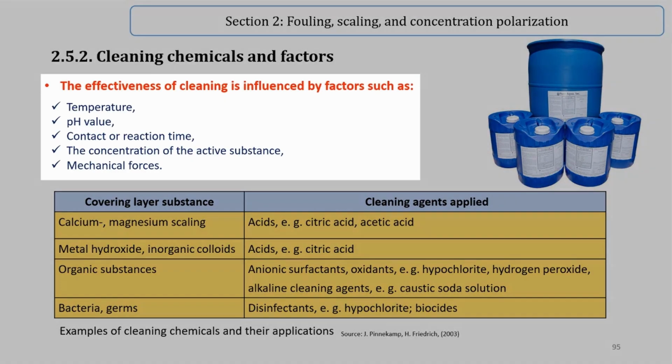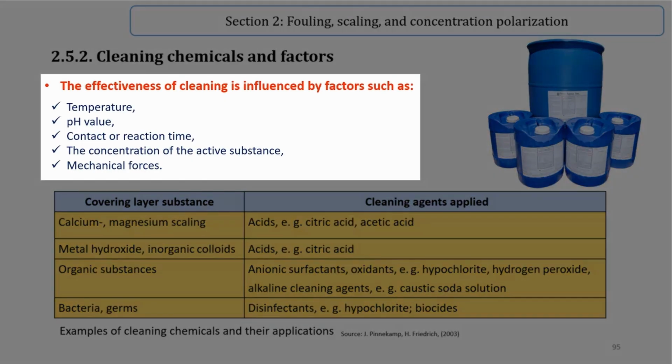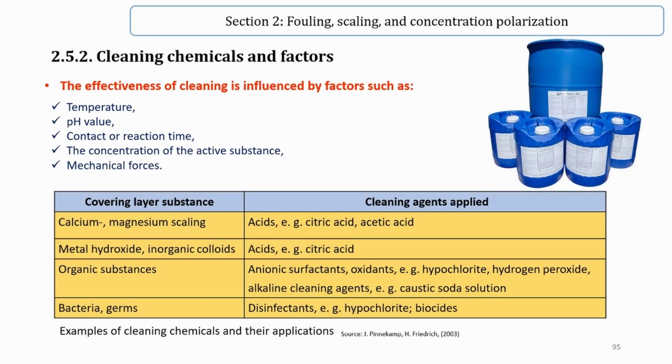Cleaning chemicals and factors. The effectiveness of cleaning does not only depend on the cleaning agents applied and their chemical activity, but is also determined by factors such as temperature, pH value, contact or reaction time, the concentration of the active substance, and mechanical forces.